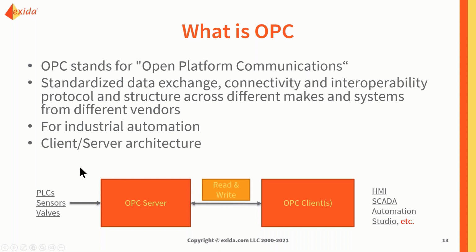For example, the different PLCs, sensors and valves send data to the OPC server. The reason we call it a server is that it acts as a kind of database, not exactly a database, but it gathers all this information so that the OPC client and other software application layers can read from or write to the OPC server.